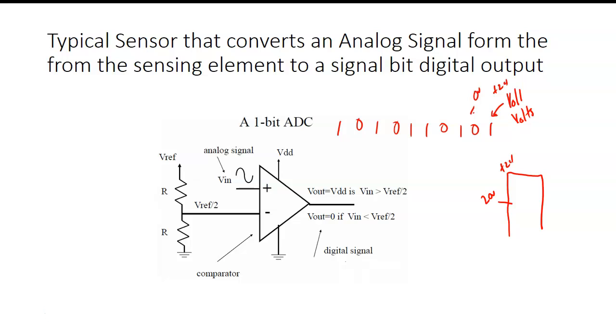Even Alabama Power or TVA, whichever one you're on, don't guarantee you 120 volts. They guarantee you 120 volts plus or minus 10%. So technically, you could be getting 90 volts at your house, and your devices still should work because you're within the guarantee. So that's what's nice about this.